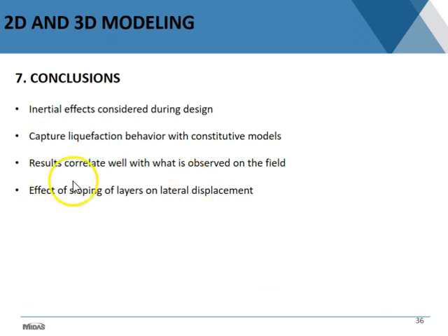And also something that I didn't point out too much, because when we developed the model in Midas, all the layers were horizontal, but the sloping of the layers plays a large role for the problem of lateral displacement. If you have enough geotechnical information, you can try to get a sense of that. If you don't have many, usually we all use horizontal layers, but this is just a cautionary message to be careful with the use of only horizontal layers, because the sloping of the layers can increase the demands coming from lateral spreading.